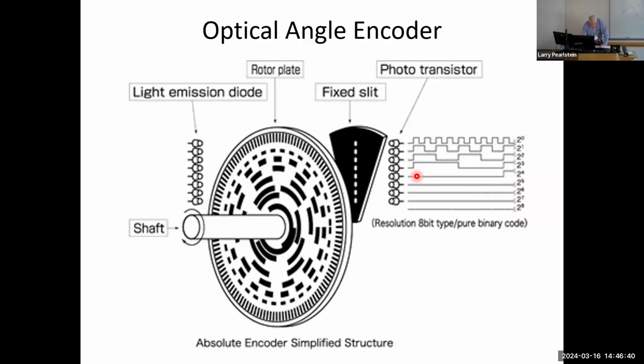Humidity. Dew point measurements have replaced most wet-dry bulb thermometers. Dew point is the temperature at which atmospheric moisture will just begin to condense on a chilled surface as a fine dew. As with wet-dry bulb, the air temperature and delta T allow you to calculate the relative humidity, though with different charts for the two phenomena.